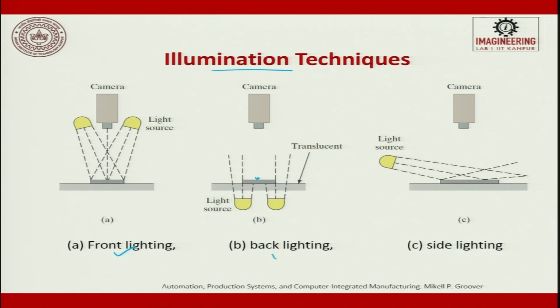So, front light, back light and side light, depending upon the reflection produced by the light falling on the object, we can also swivel the light source at an angle such that we get the best out of it. For example, when we are looking at the flatness of a silicon wafer, if you keep the light at a 90 degree angle, then you will not get to see the image because it is highly reflecting. So, in those cases we go for an angled light source.